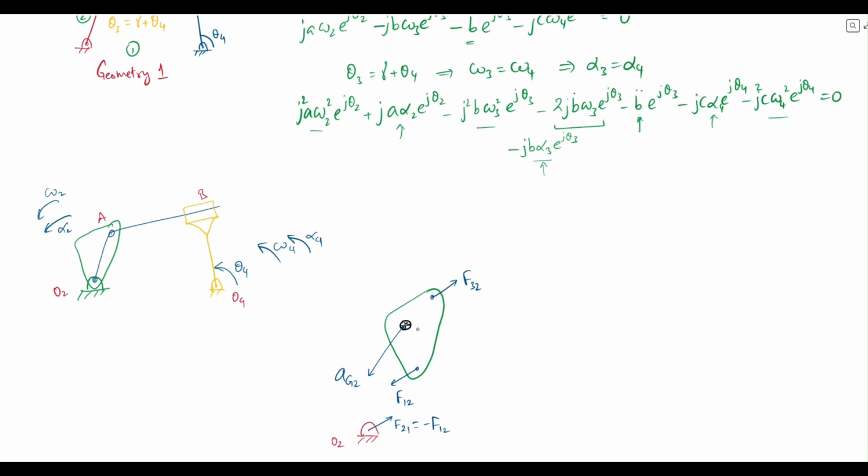We can identify the positions of these in either a local rotating or non-rotating coordinate system as per our convenience. I'm just going to use a local non-rotating coordinate system at the CG. So if x and y, we have a position like this, which is R3,2, and we have a position like this, which is R1,2. We can consider there is a torque T1,2, which keeps everything in dynamic equilibrium, and these will all be the forces of the crank.